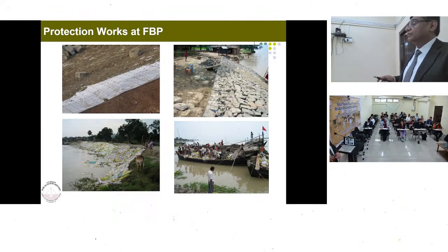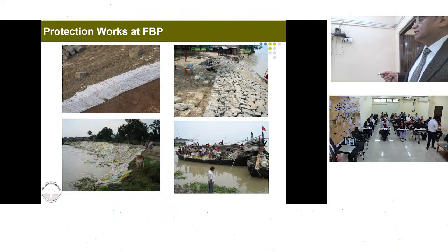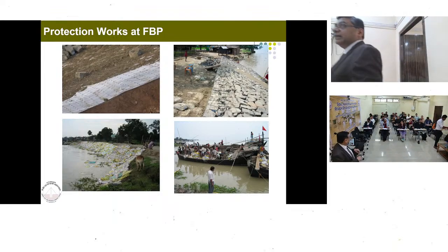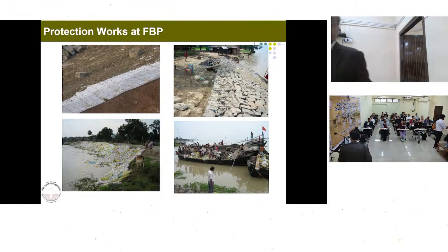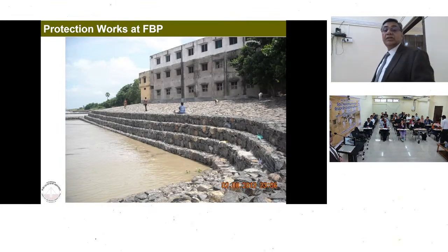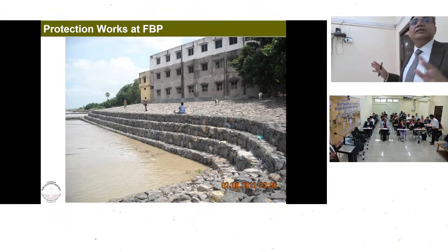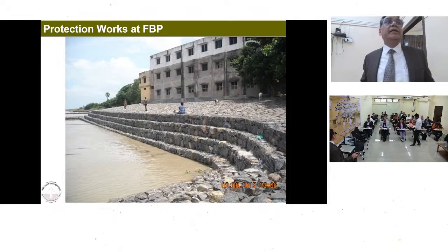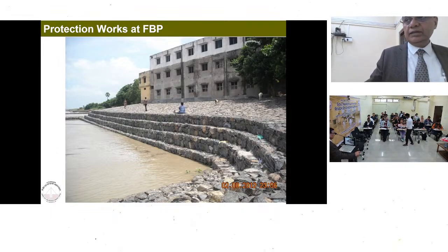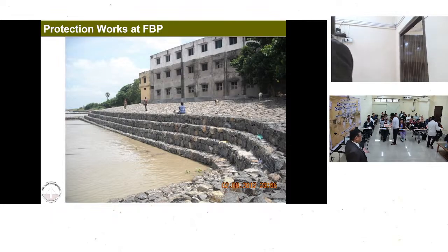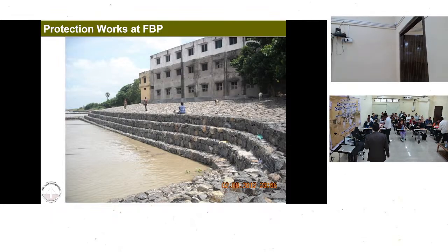It worked. At some places, even geobags were used, and again, these geobag systems were filled up in nylon crates. They were also dumped, and this is how the final system came out, in relatively much better condition as compared to the older one. Still, there are problems. Still, there are places wherein erosion is occurring, but those regions are now reduced to smaller pockets.